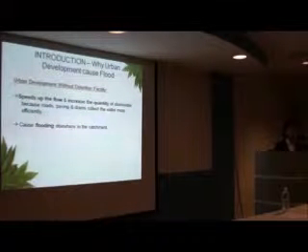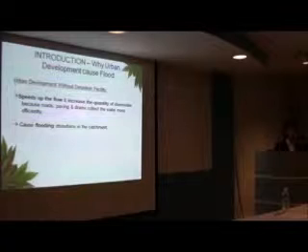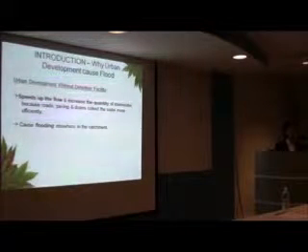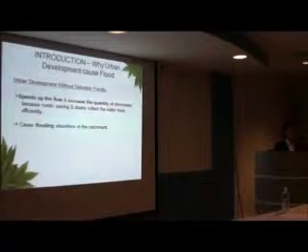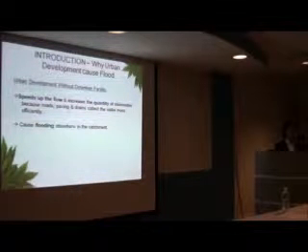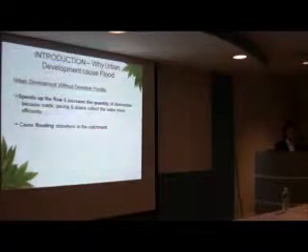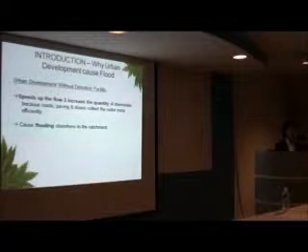Speeding up the flow is because the drain is already lined. It's not like a lateral stream flow, which is slower. And it increases the quantity because all the previous pervious area has been covered with hard surfaces. Like roads and housing areas, those areas are not pervious, they are impervious. So development will increase the quantity and speed up the flow. This is the reason unplanned development will always cause flood.